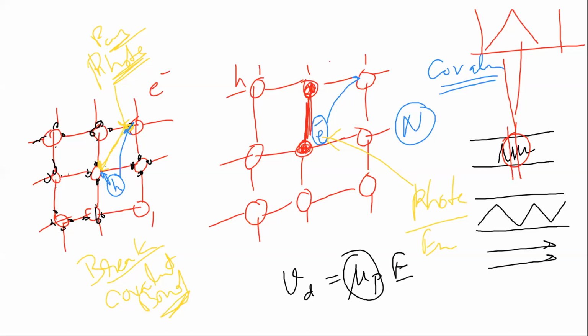And just to add a little bit more, a philosophical thing, in the sense that we don't always want only fast devices in a circuit, right? There might be times when we want a good resistor. If I want a good resistor, I want to use a P-type, because for 2.5x less area, since the mu's differ by 2.5x, I get the same value of resistor.